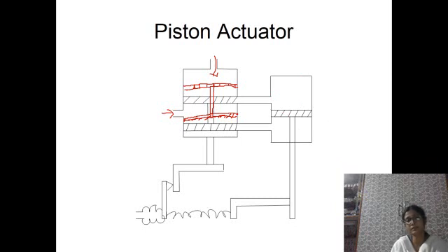The input signal can flow through this, and when the pressure increases, then the plug, the piston, will move downward, and as it goes downward, it will in turn close the outflow path through these paths.